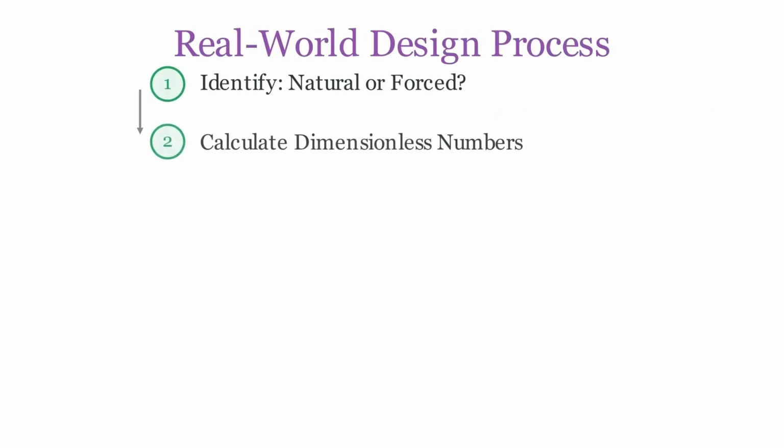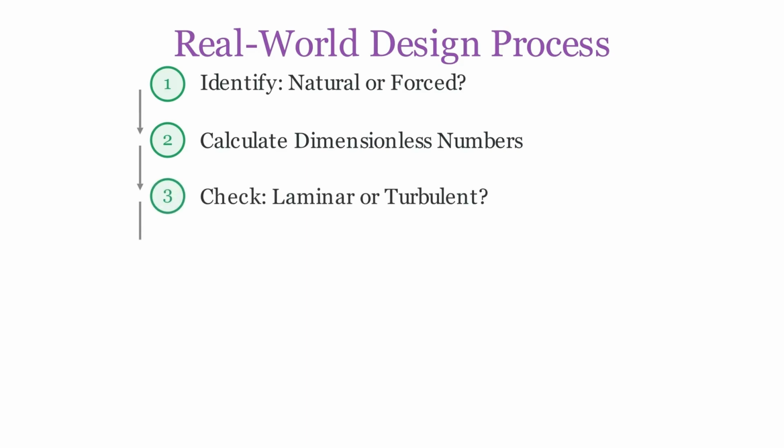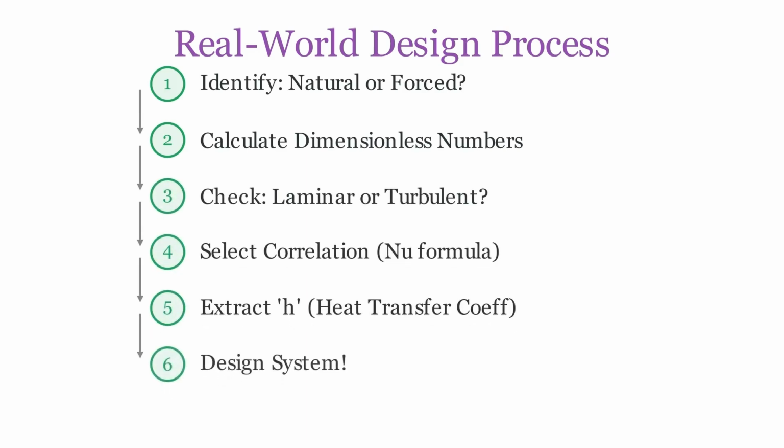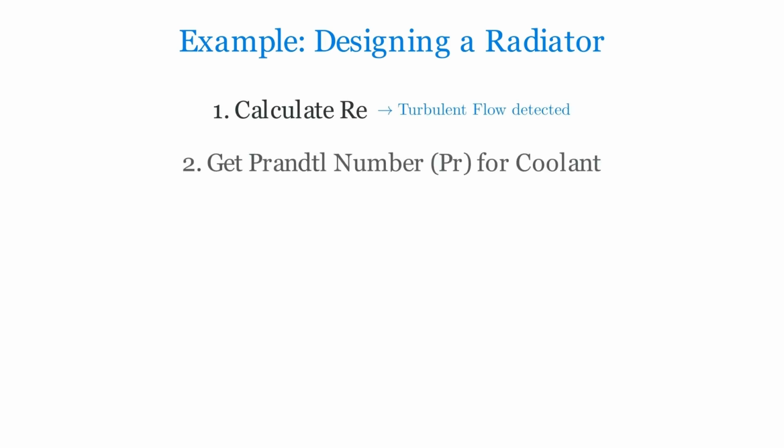Real-world design process: identify natural or forced convection. Calculate relevant dimensionless numbers. Check laminar or turbulent. Use appropriate correlation to find Nu. Extract H, heat transfer coefficient.